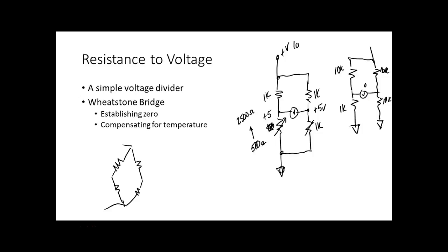Yeah, if the ratio, and they have to be, usually we take the top one and divide it by the bottom. So it's 10 to 1. Well, the one on the other side is 10 to 1. It has exactly the same ratio. So that means these two resistors are going to drop the same voltage. This guy here is going to drop 1/11 of the voltage. This guy over here is going to drop 1/11 of the voltage. If both of them drop the same voltage, then I'm going to measure 0 there.